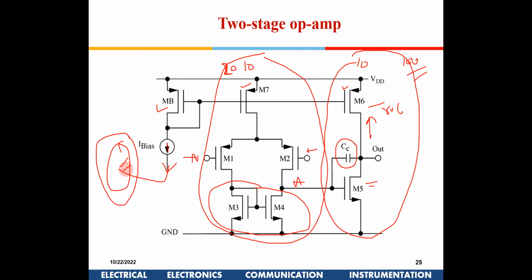I initially wanted to cover this for your course, but I guess there is no time available. Probably if I take advanced analog IC circuits, then I will talk about band gap reference there. For our assignment, we need to have this I bias also, right? Yes, you can have an I bias, and then probably give a ground out here. Or you can simply connect a resistance here instead of this current source, and you can get the desired currents.